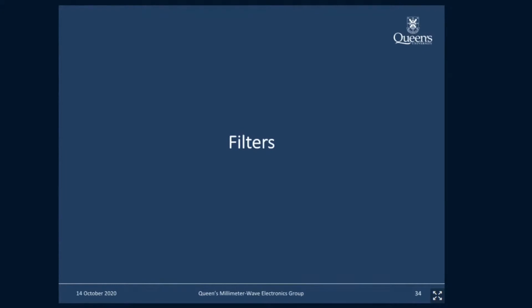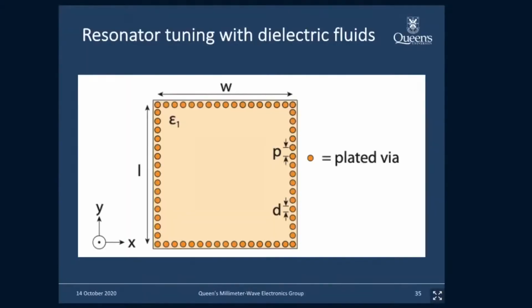The extra step, and it's a challenging step, is of course you have to then convert that equivalent circuit model into a physical structure consisting of physical resonators, waveguide type resonators that will give you the filter response, right? So that's actually the extra fun step that we take, so to speak.